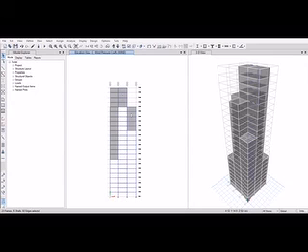Select the visible shells and apply the wind pressure coefficient of minus 0.25 in the similar manner. The wind load on the sides A and B as per IS code has been applied.